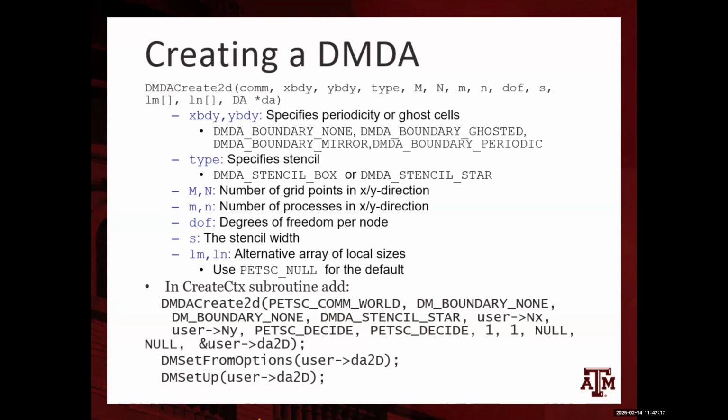So for the stencil width, you said that since we are having a 5-point stencil, we just have to put 1 because that one node stores all the ghost information. Yeah, so think about it. For example, this is your boundary, and we are using a 5-point discretization, right? So this node is within one of the ranks.